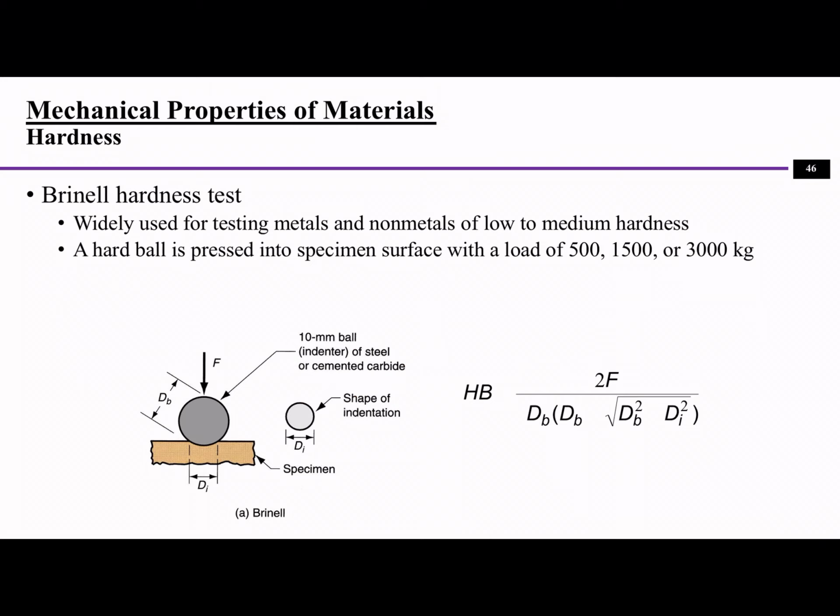It is using a ball indenter. It's ball shaped. So what happens is that first you set the ball on the surface, and then you give an initial force, or initial load, to make sure it penetrates the material to a certain depth. And then it will keep increasing the load, and you calculate, with the increasing load, how much depth it can go,